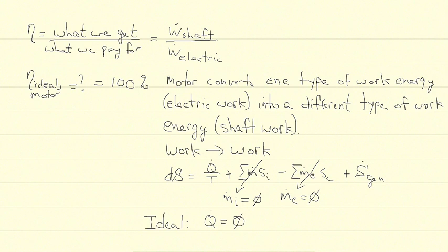All of these are losses, all of these are irreversibilities, and if you have any questions about that, you can refer to the irreversibility auxiliary lecture. The point is that this Q dot represents all of the losses in that motor system. So if we want to create the ideal motor, we have to perceive there being a Q dot equal to 0, without any heat transfer losses.